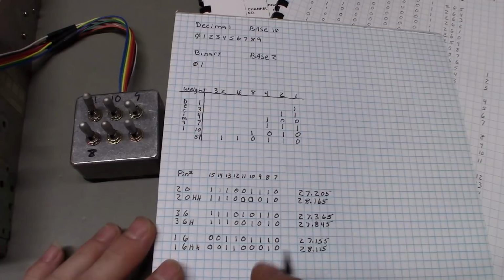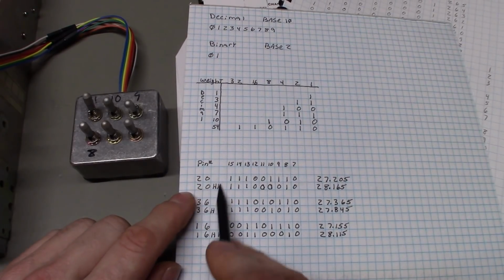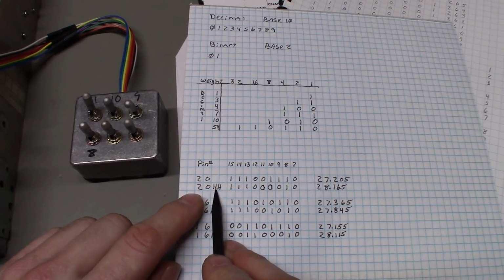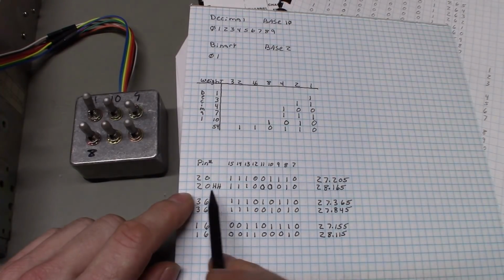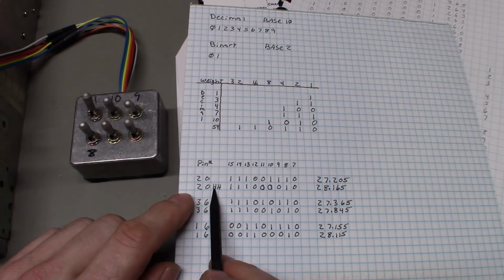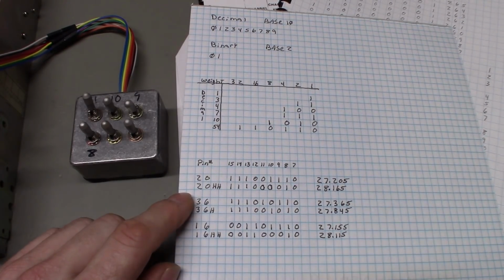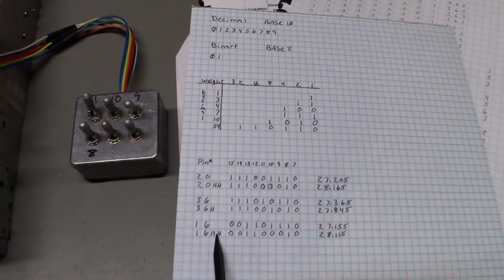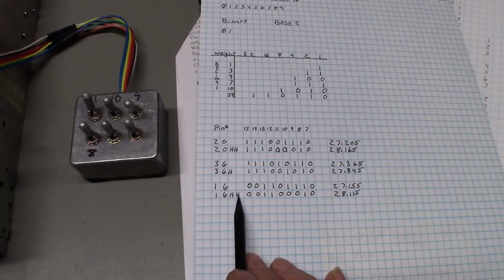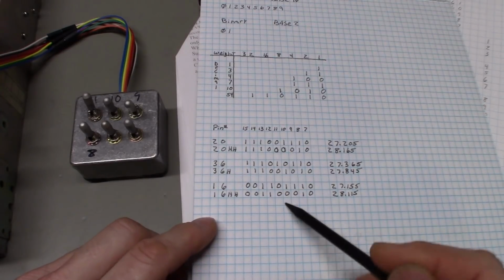But as far as programming, I wrote this one down. Yeah, I can't get 20 high. If I set the VCO voltage to where the PLL will lock on 20 high, then CB channel 1 will not lock. So actually, the highest I can get is like channel 16 high. So let's do these two.